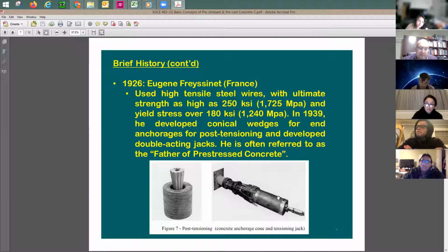Now you're going to put the cable through the concrete. And from the name, we call it pre-stress, which means that you're going to be applying some tension or some stressing to this cable or tendon. When you do this, the cable itself is going to be anchored to the concrete. What does it mean by anchored? Just imagine in conventional reinforcing rebars, the anchorage is provided by just putting some hooks at the end of the rebar, like a 90-degree hook or 180-degree hook, and that's it, you're done.